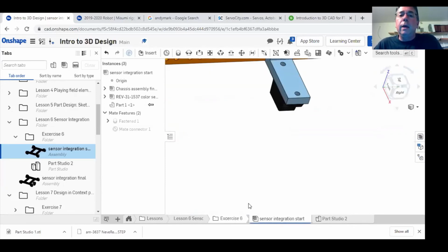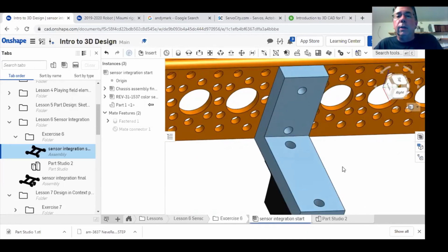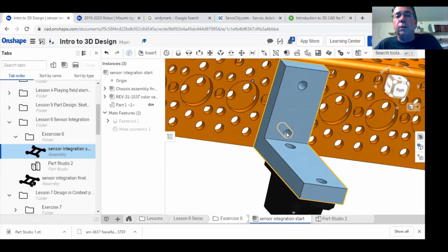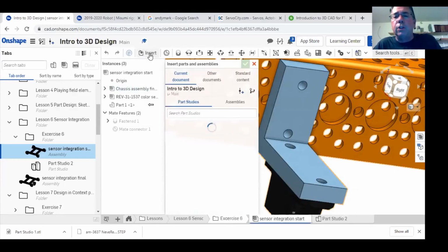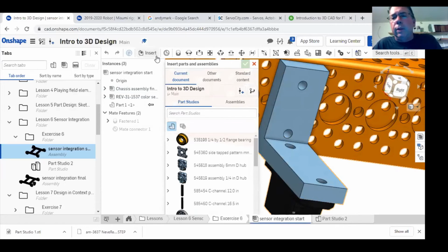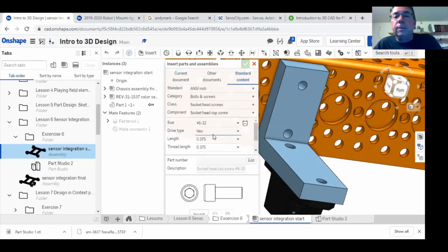Now, all of those that are looking at this, you're going to say, well, there's a problem down here because you'll never fit a fastener into there and into that hole simultaneously. And that's a true statement. I designed this part just to point that out. We constantly fail to factor in the size of the fastener and how it gets inserted into a part when we're designing our robot. So I just want to bring that to the forefront so that you guys can all keep that in mind. It's a common problem that everybody, I'm sure, has.